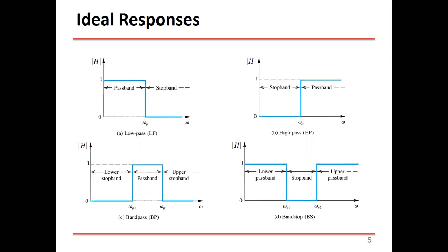No, what's the point if you make a gain of 1 or 2 or 10 to everything? This is just a constant. This is not a filter. We cannot call it a filter. If you provide a constant gain for all frequencies, this is just an amplifier. You just build an amplifier, inverting or non-inverting, with 2 resistors, and that's it.